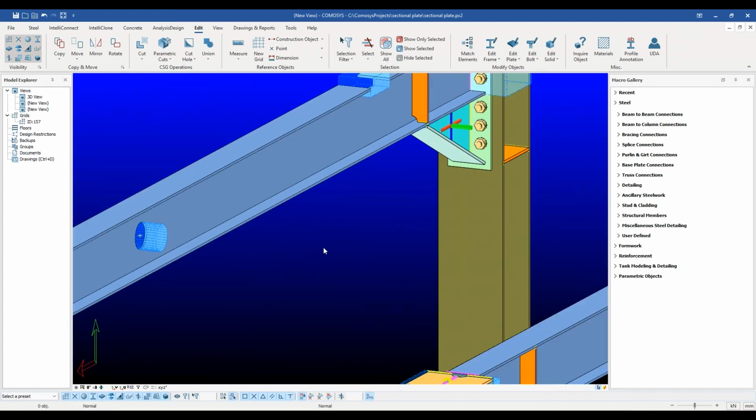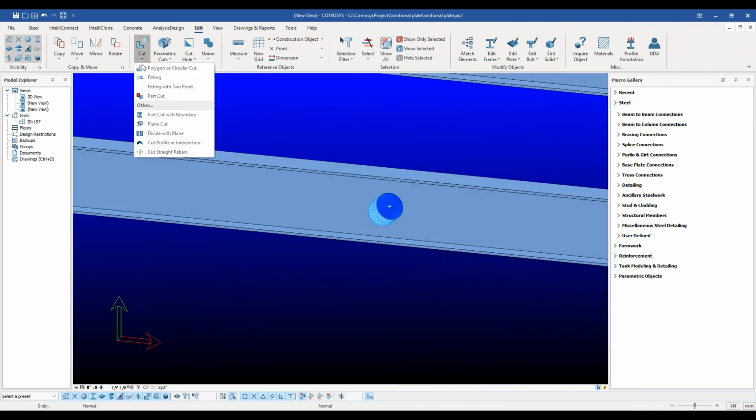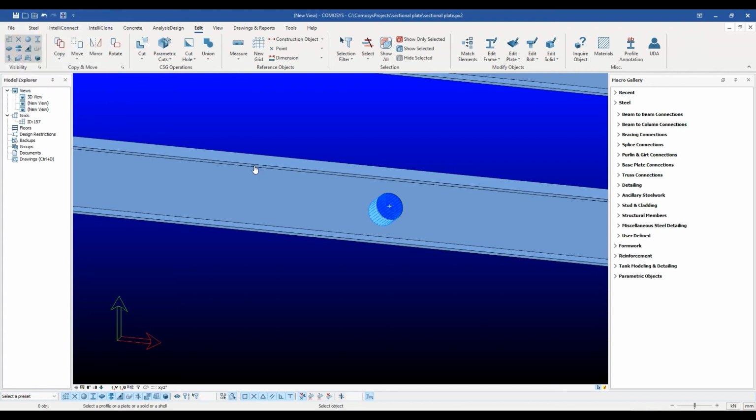There is also a section count here, which defines how accurate the circle will be. Usually a number around 32 gives a good result, but it should be noted that smaller numbers like 5 or 8 etc. can be used to create pentagons and octagons etc. Let's draw a polygon here by using the direct entry method.